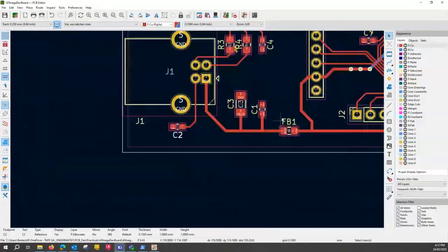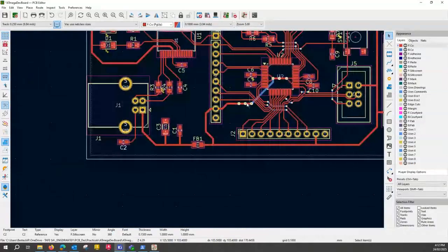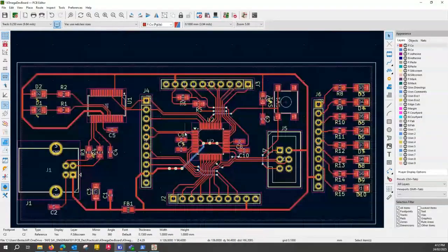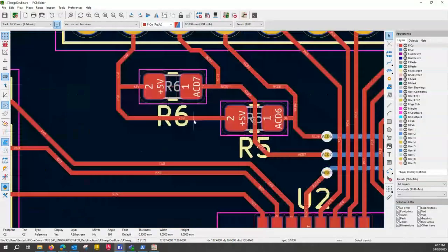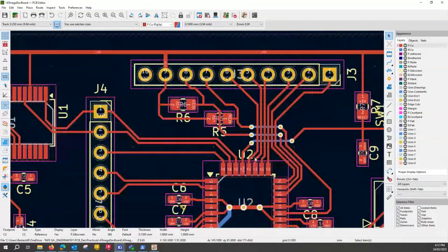Most of it should be okay, actually. The position of those, they're pretty close, but they're not too close. And the designated text can go over tracks. There's no issue there. It's just paint, which is painted over top of finished boards, so they'll be clearly visible on the top anyway. That one is fine.